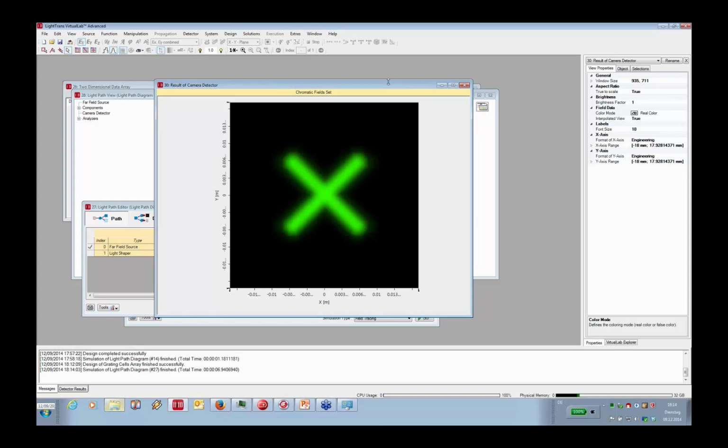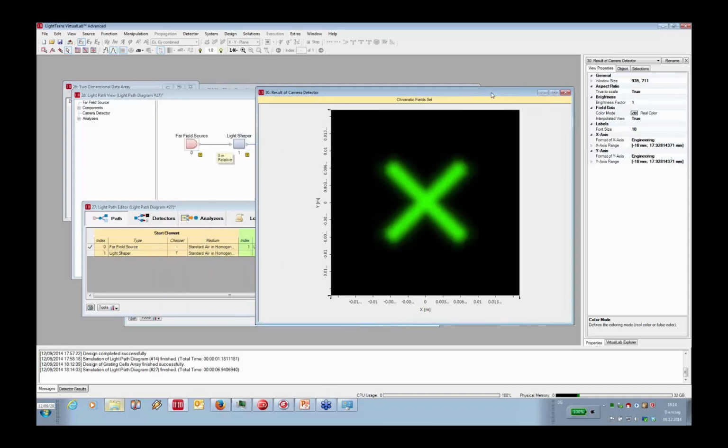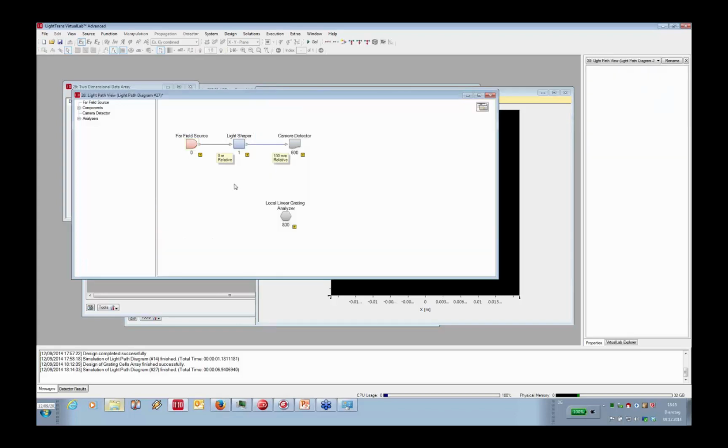I would like to mention that if you would like a more accurate simulation of the light pattern, then you probably need to use the grating toolbox in the background. For this simulation, I assume that the diffraction efficiency of all gratings is constant, independent of wavelength and incident angle. But we know that if you have very small gratings in the range of the wavelength of light, the diffraction efficiency can change depending on the grating period.